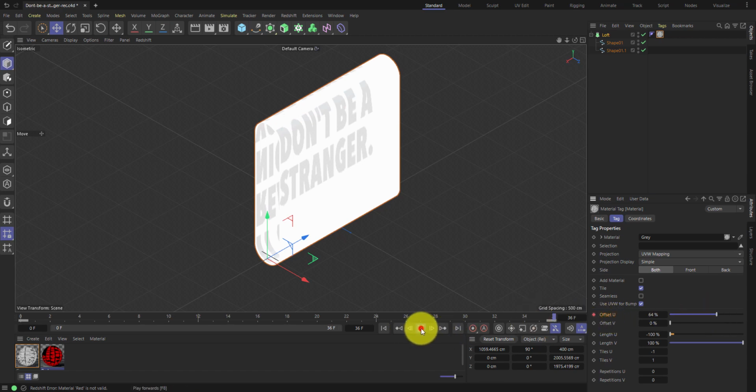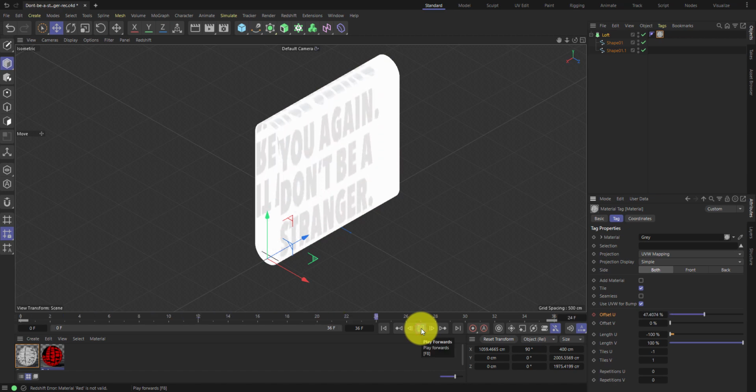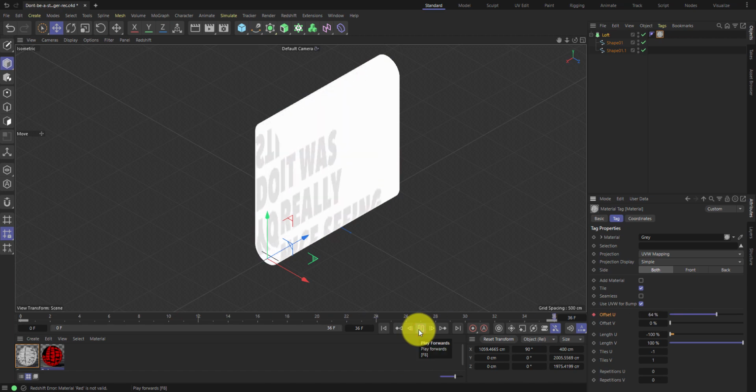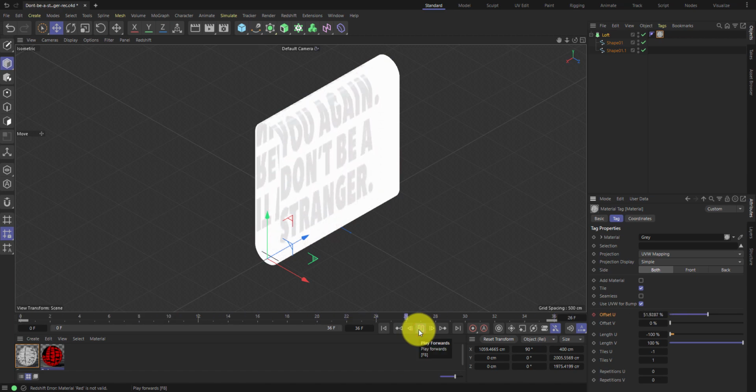And if we play that back, there's a little bit of animation. This isn't the exact timing of the animation, so you always want to go to the scene playback settings here and uncheck all frames. We want to use the scene frame rate to play back these frames so we can get a good sense of the timing. So that's the actual timing, 3 seconds, and you can see the easing is built in there.